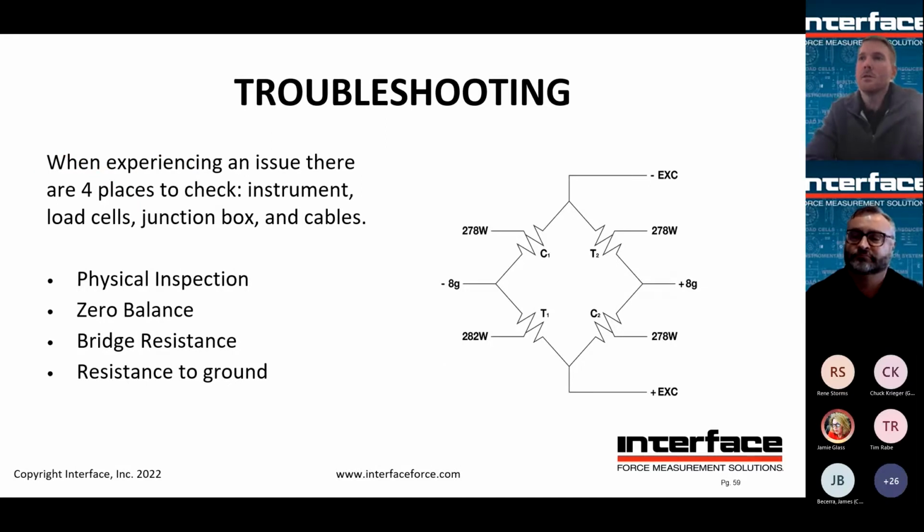So really there's 4 places to check. The problem is going to be in the instrument, the load cells, the junction box, or the cable. First thing is physical inspection. How does it all look? Is it rusty, corroded, oxidized?